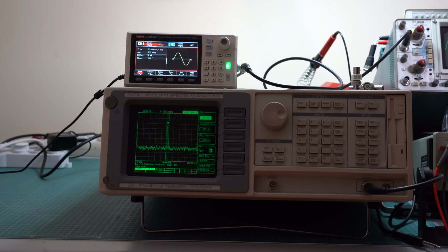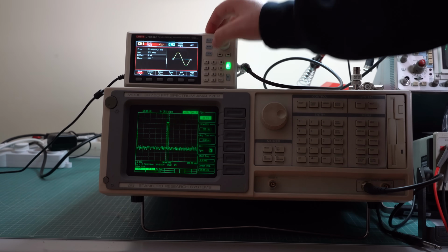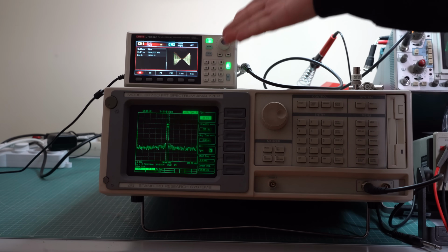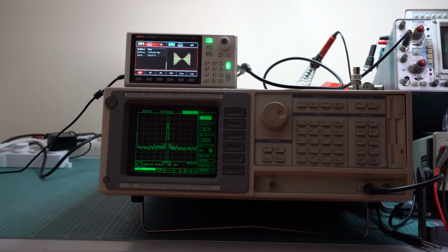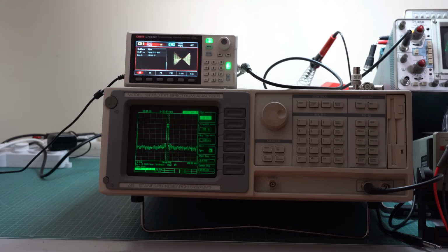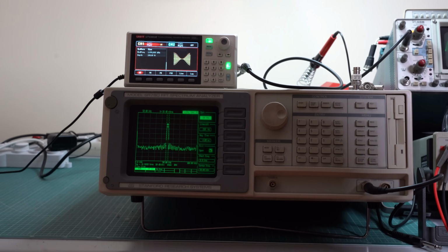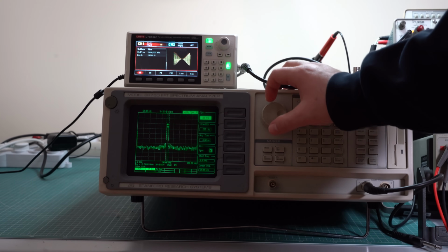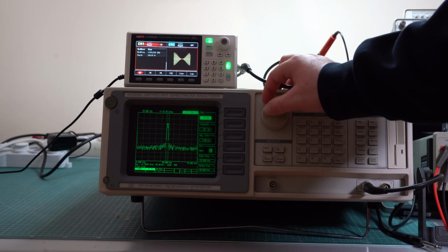And such an example would be if you have a signal that's amplitude modulated, for example. So let's turn on amplitude modulation here. Now we have a 50 kHz sine wave that's modulated by a 1 kHz sine wave. If you look at the spectrum analyzer, it basically looks like a single peak, so you don't really see what's going on here. The best solution to this is to just reduce the span in our area of interest until we can see the sideband signals.